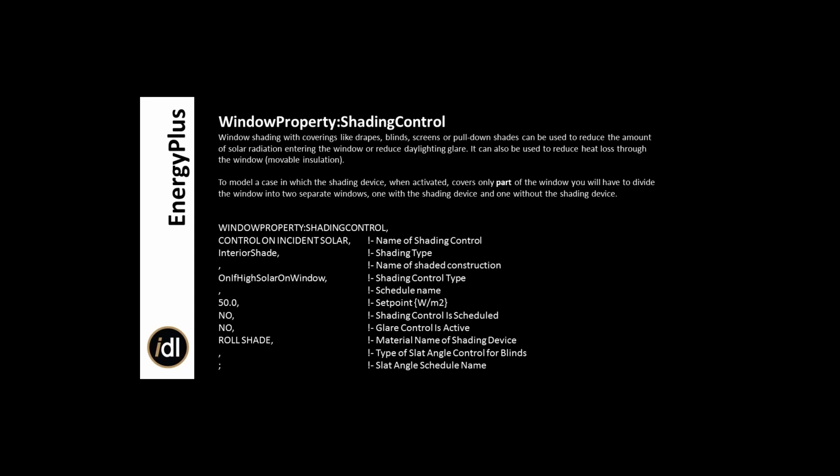And if we want to shading control a schedule, you can say yes. And if the glare control is important, you can put yes there. Also, we have a material name for shading device that I will explain on the next slides for you. And if you have slat type blinds, you need to assign those two last lines.